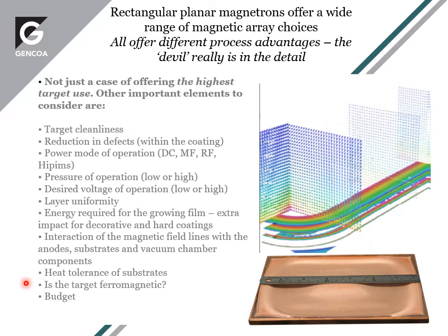And then we have practical limitations, such as for ferromagnetic materials that need to be sputtered, such as nickel and iron. The magnetic field from the magnetron gets absorbed in the target, so projecting the field through the target becomes more difficult. And then obviously very important is budget, so we have various sophisticated magnetic designs, but they're not always appropriate and not always needed for certain situations.